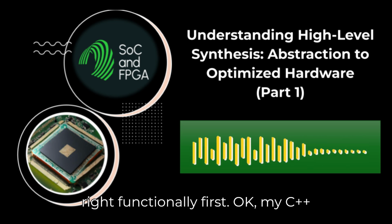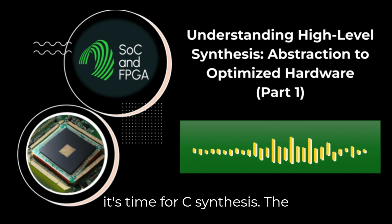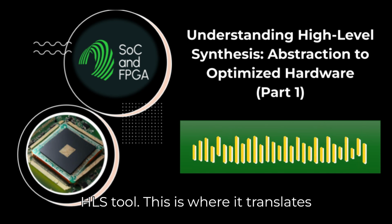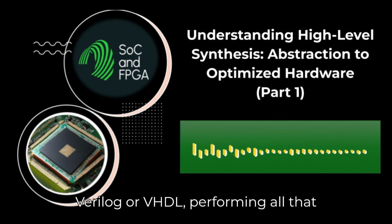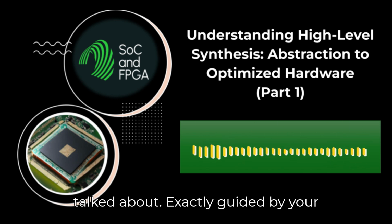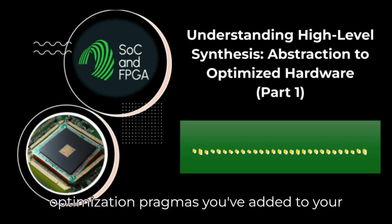Okay, my C++ code works. The test bench passes. Now it's time for C synthesis, the translation engine. Now you invoke the HLS tool. This is where it translates your verified C/C++ function into RTL, Verilog or VHDL. Performing all that scheduling, allocation, binding we just talked about. Exactly. Guided by your target clock frequency and any of those optimization pragmas you've added to your code.